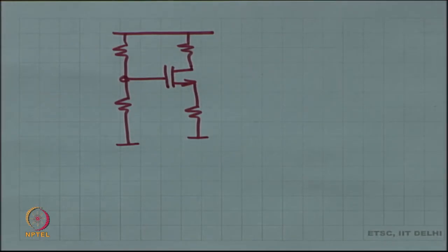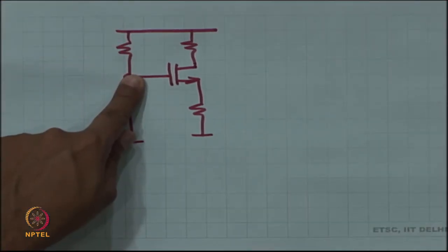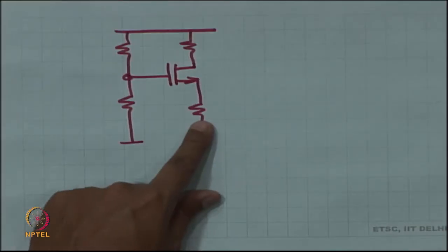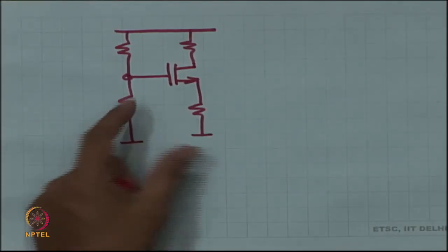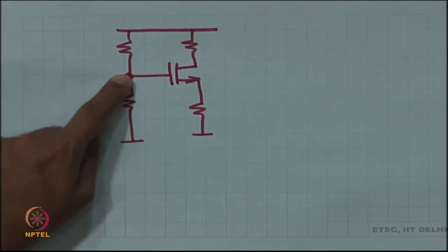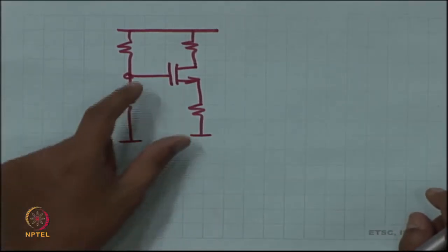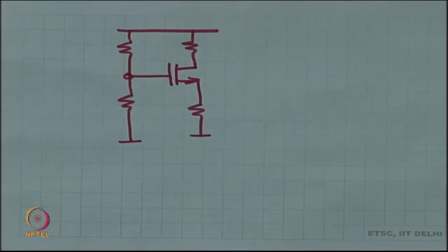And we had a long discussion on why this structure looks like this, right. So, on this side you establish the voltage at the gate, and this resistor is important because otherwise the current is too sensitive to this voltage, to this precise operating point. To reduce the sensitivity, we place this resistor, and now you have got a much more stable DC operating point. Okay.